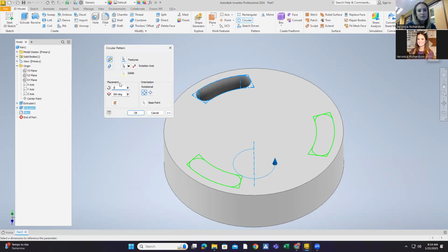You may want to cut out just 3 or 4. So in the settings box, you can change that quantity. The nice thing is it evenly spaces them out for you, and it makes them all exactly the same size. Again, we're just leaving it at 6. So all you have to do is go back into the settings box and press OK.